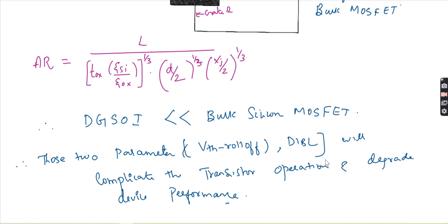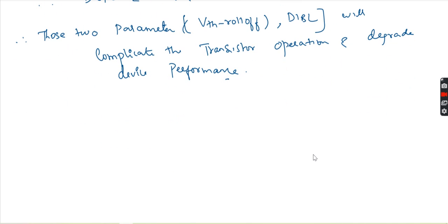So still, if you need to minimize the short channel effect, you have to use a sufficiently large aspect ratio, and some novelty in the structure can also be used. Nowadays, not only double gate has come; presently the novel architecture, FinFETs, are used.